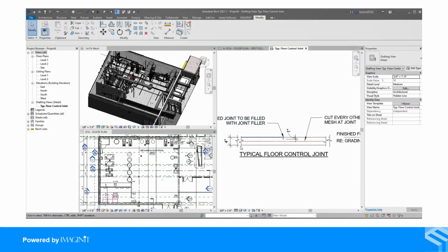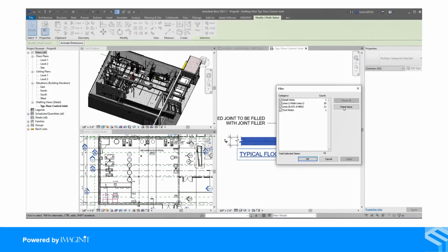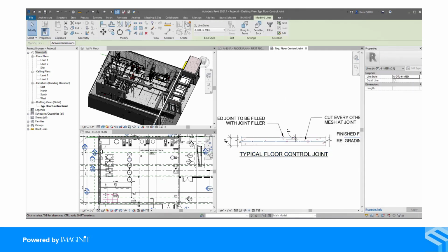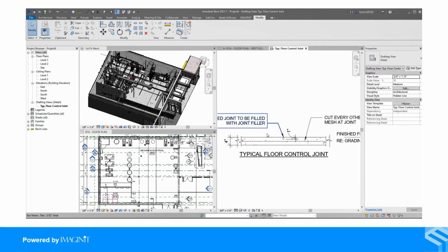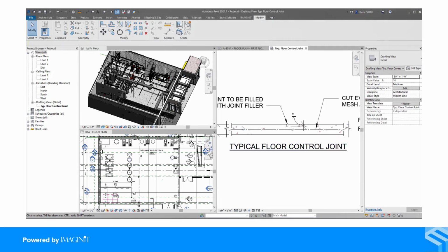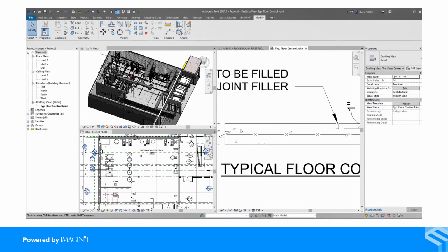And so there I've made all of those wide lines. If I do this again, we can see that now I only have one layer left that I haven't changed. So let's go ahead and just make that one my thin lines in this case. So I've got all this line work pretty much taken care of.